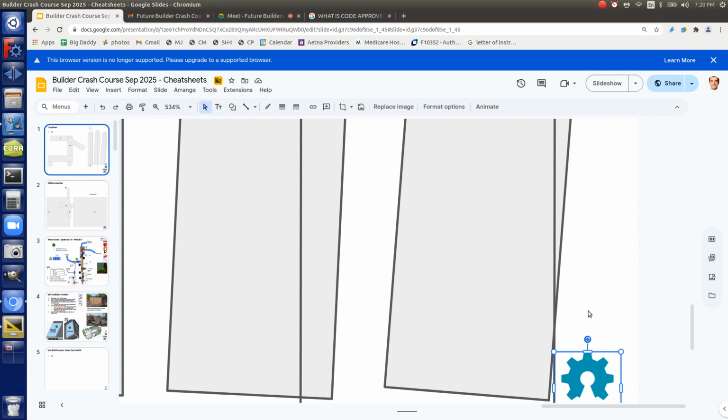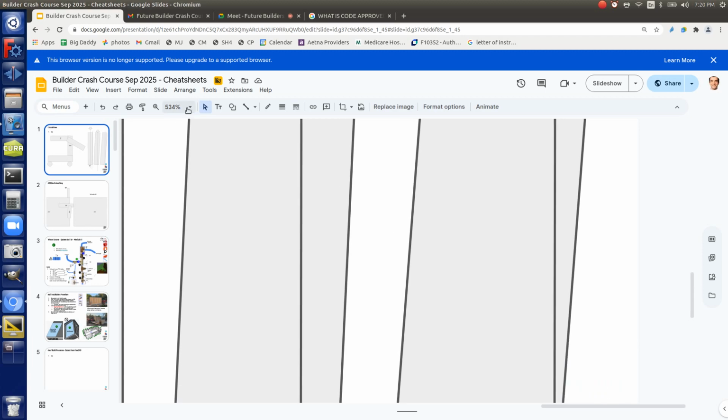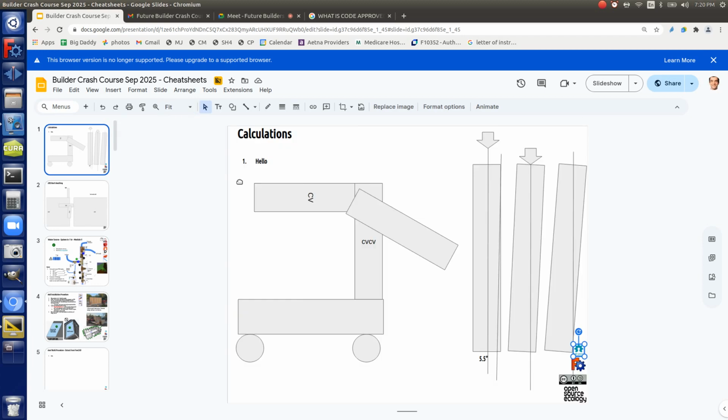But by code, let's just say half inch. But for your personal understanding, say by accident you had a case comparable to this and you're asking, okay, that's bad. Is it catastrophic? Okay, well, is the rest of the wall good? Is that only maybe one wall section out of all of them, where you've got certain loads, and all the other walls can hold perfectly fine? So if you had this mess up and you're evaluating, it's going to take you say $1,000 or $10,000 to fix it.